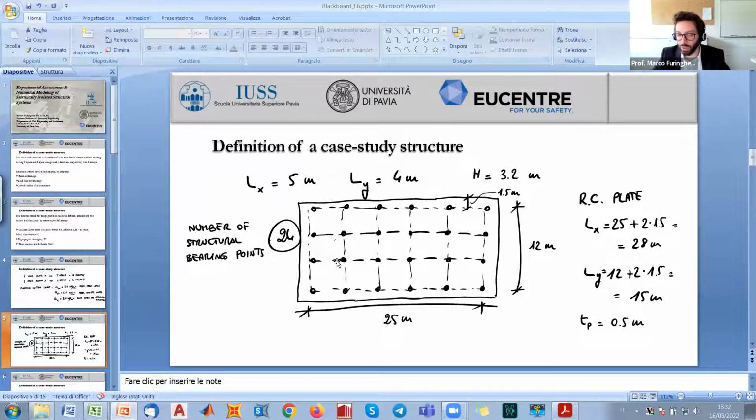I think that the best choice will be the LY beams, the edges along the y direction, represented by isolation devices, because in this way we are maximizing the distance between isolators and the stiffness center of the overall isolation system, so that we are automatically increasing the torsional stiffness of the system.